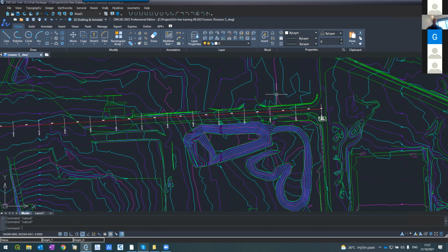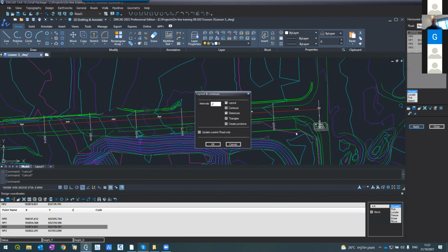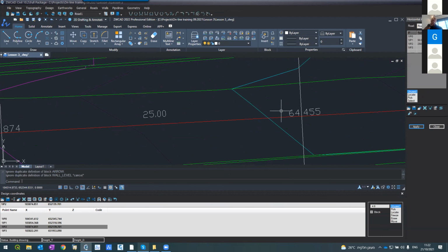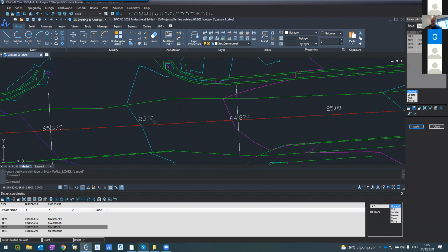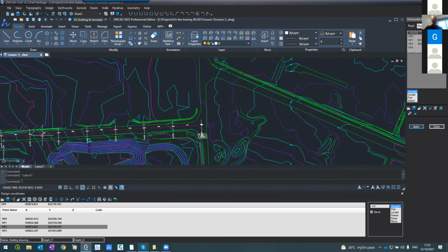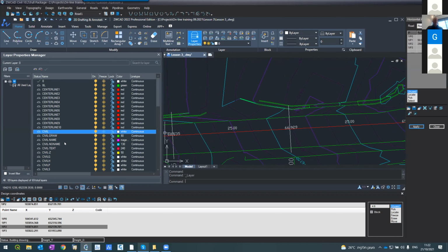I'm back here. If I want to see the profile projected on the layout, on the horizontal alignment, I go to roads, horizontal alignment, press OK, apply, and OK. Then I will see the profile data here. Have a look. You see? All the data from the profile were projected here on the cross section on my layout. Of course, these are all in layers, so we can give this one sec data, sec data.